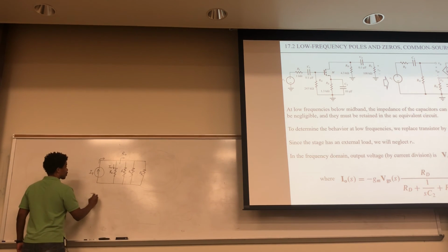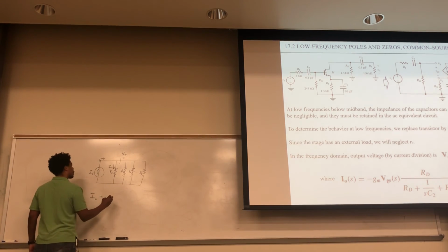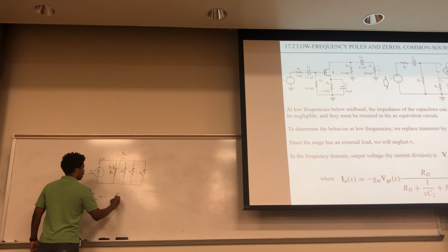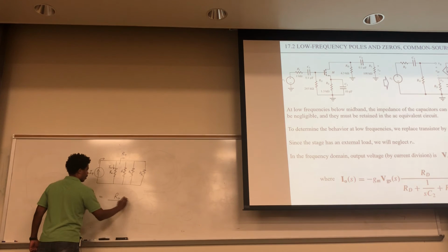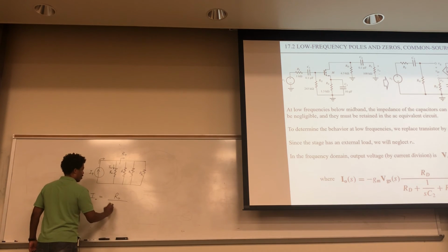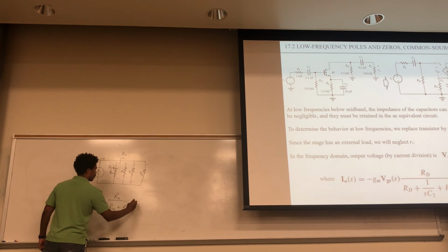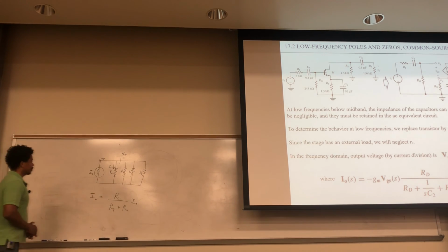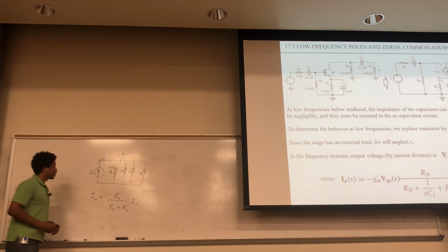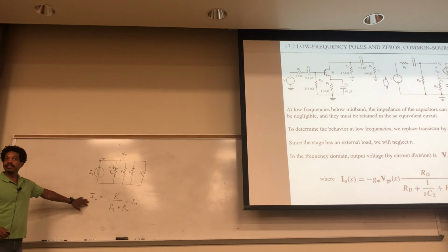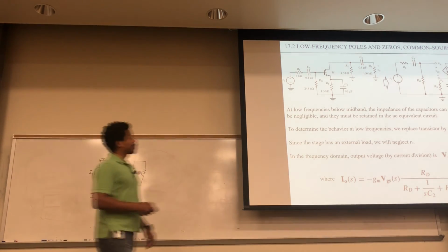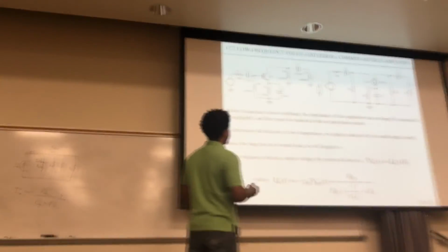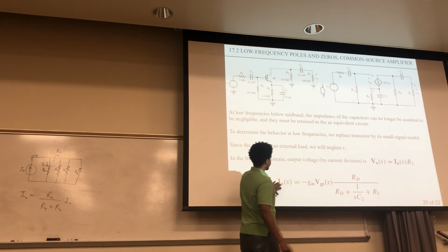So this current I0 is equal to the total current times the total resistance looking along that direction, divided by RT plus this resistance right here, times what you're starting with. Yeah, I think that's right. You guys agree with this? Yeah? Okay, cool. So that's what's happening right here, and that's where we're getting this expression from.